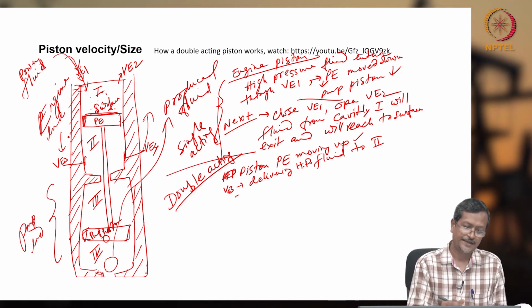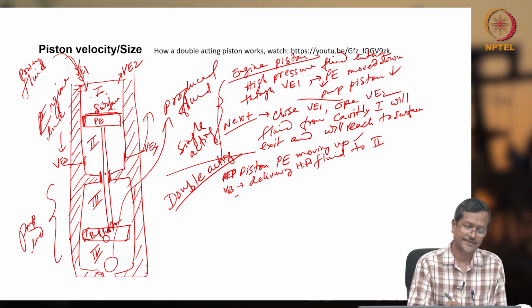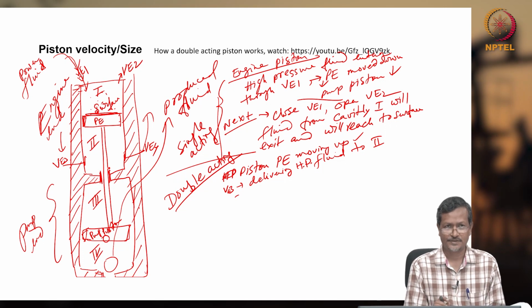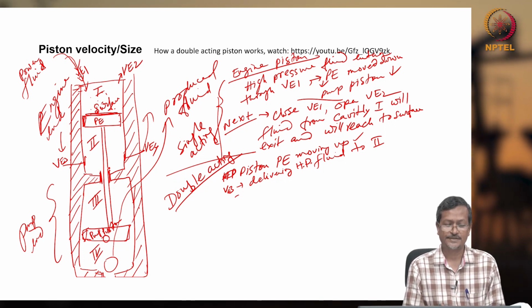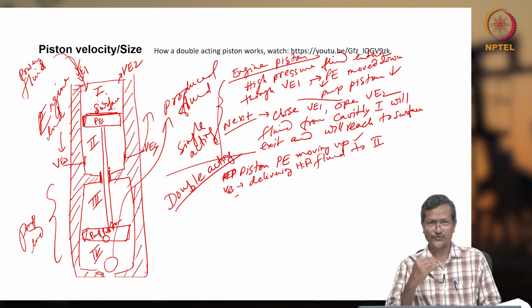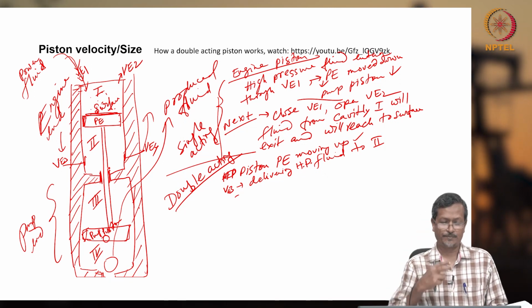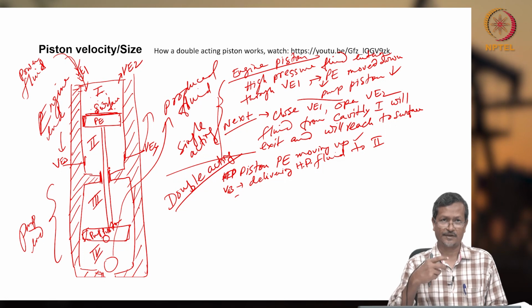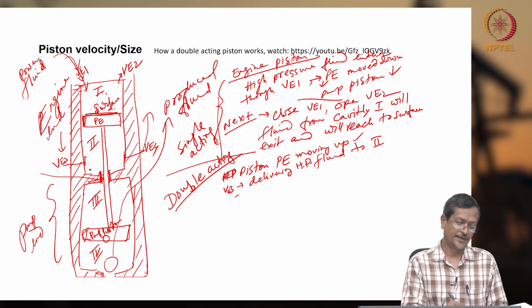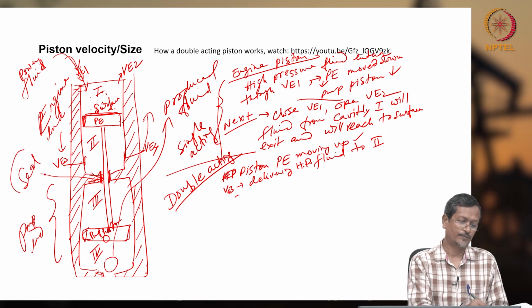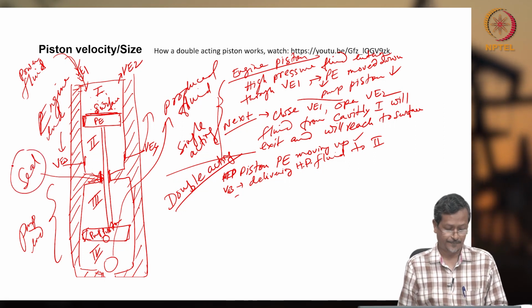And there will be a sealing section here, a metal to metal seal. Sometimes elastomer and other seals can also be used, but normally a metal to metal seal will be there. If a very high amount of leakage is there, then your power fluid, which is on the engine side, and the produced fluid on the pump side will mix up. So normally there will be a sealing section here, so that both fluids do not get mingled.